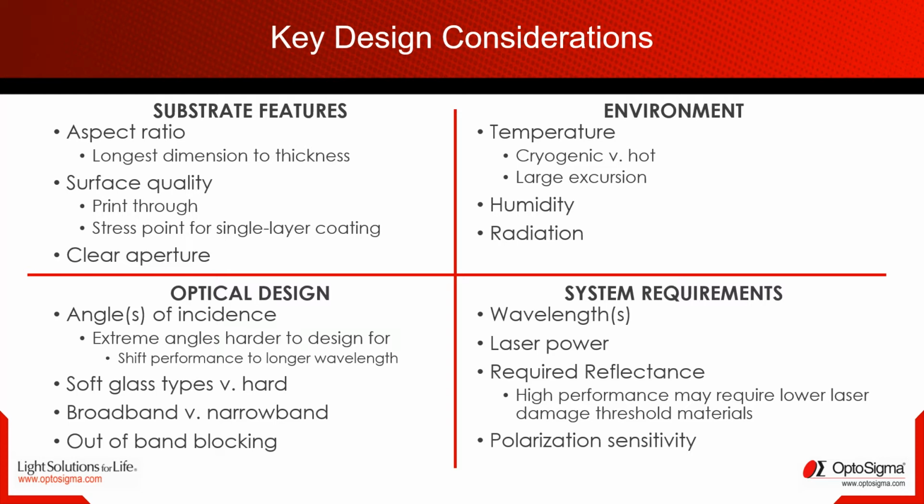As laser power goes through your system, different elements will see different power densities as the beam is expanded and reduced, and could cause survivability issues with an optical coating. It may dictate the use of oxides only, and that again may be a performance trade-off issue.